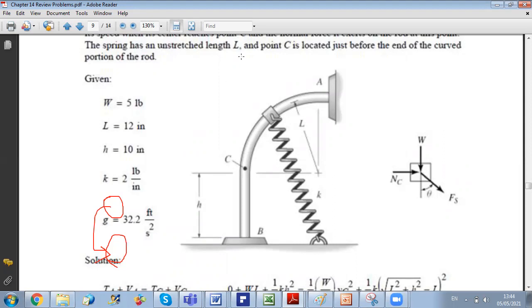You know why? Because it depends on the value of the spring force. Agreed? It depends on the balance, because in the end N is equal to, if you get the value of NC, mv squared over rho. So N is m vc squared over L, which is MAn, minus the projection of Fs, because we take it in the normal direction, so minus Fs sin theta.